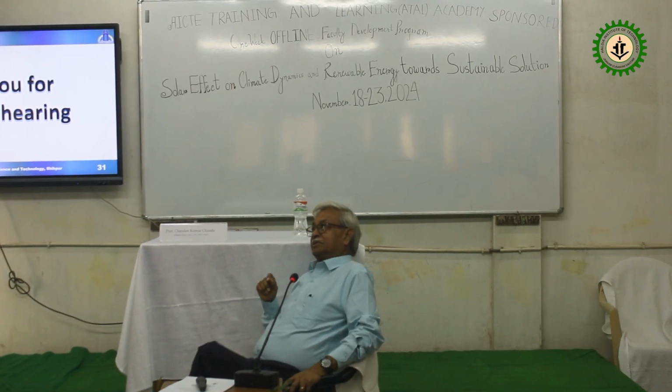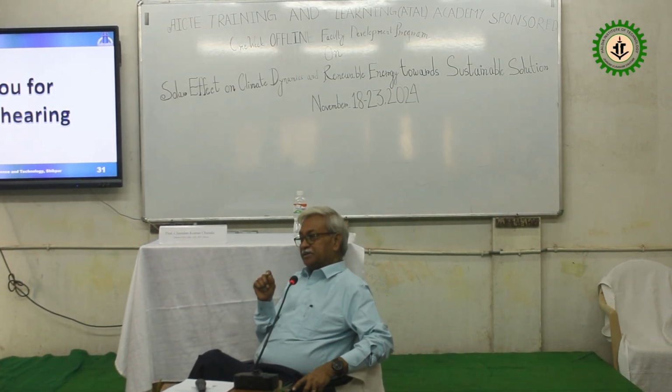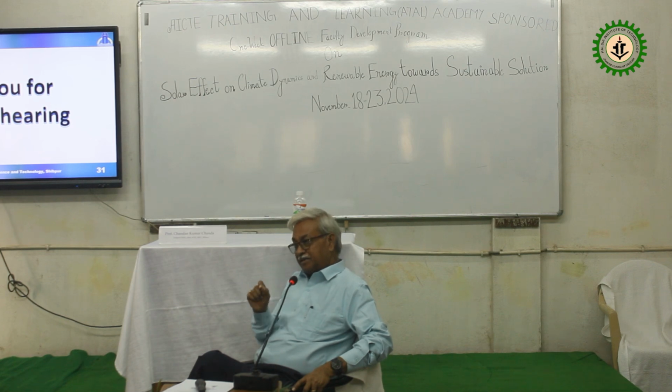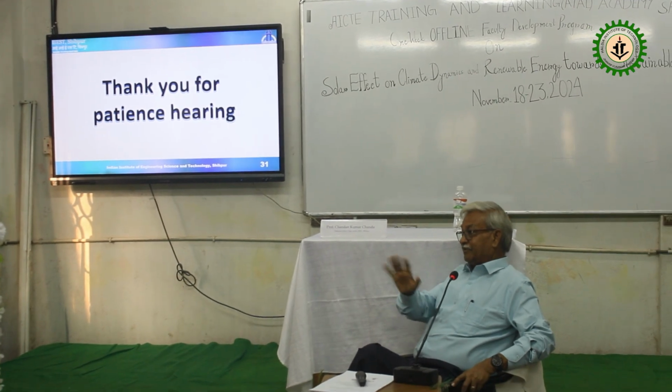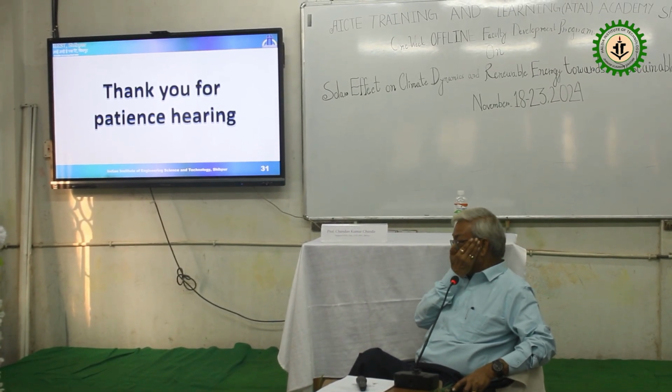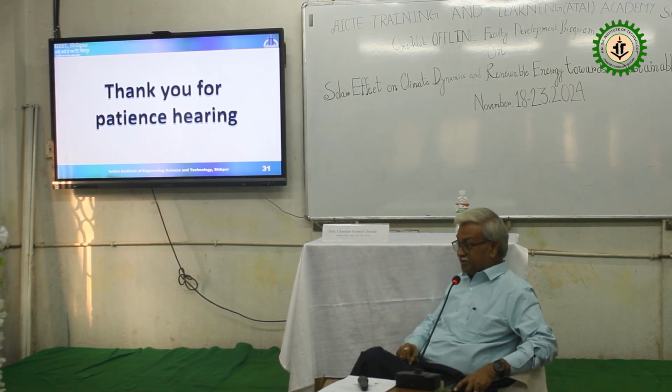ROCOF means when the inertia changes, then the frequency changes. Frequency is the thing which is related to the electricity. If the demand goes high, it cannot give the supply, or the demand falls down and the supply is in surplus mode, the frequency deviates. That frequency deviation is not the only thing. Whenever we are penetrating or integrating renewable energy, we are not adding inertia, rather we are deteriorating the existing inertia in the system,